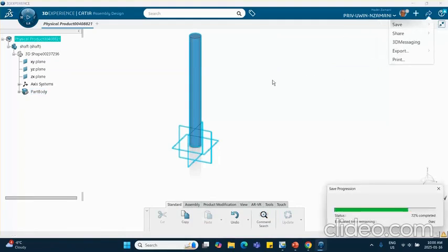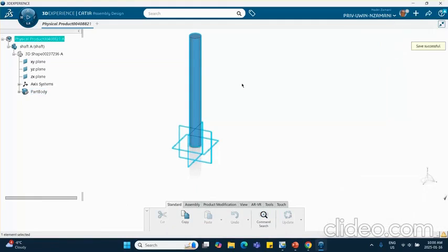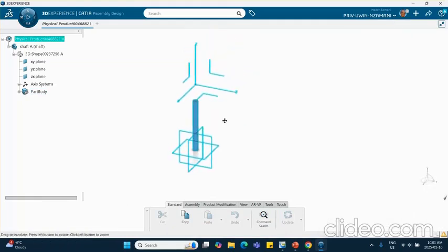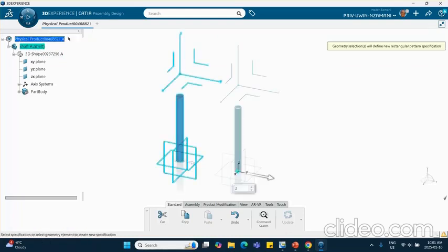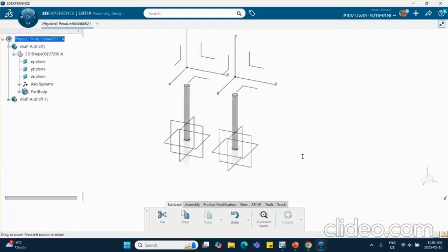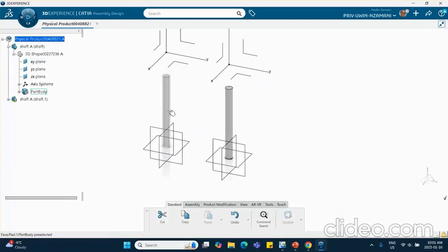Now the other shaft is going to be just like that, so I can actually create another one just like that, or do a copy paste, etc. But the alternative is also, if you're at the assembly level, you click on this shaft here, you can instantiate it, and two copies is good enough, so that's good. So basically we have created two identical shafts. This was the original one, this is the one that's duplicate of that instance of it, and we move on.